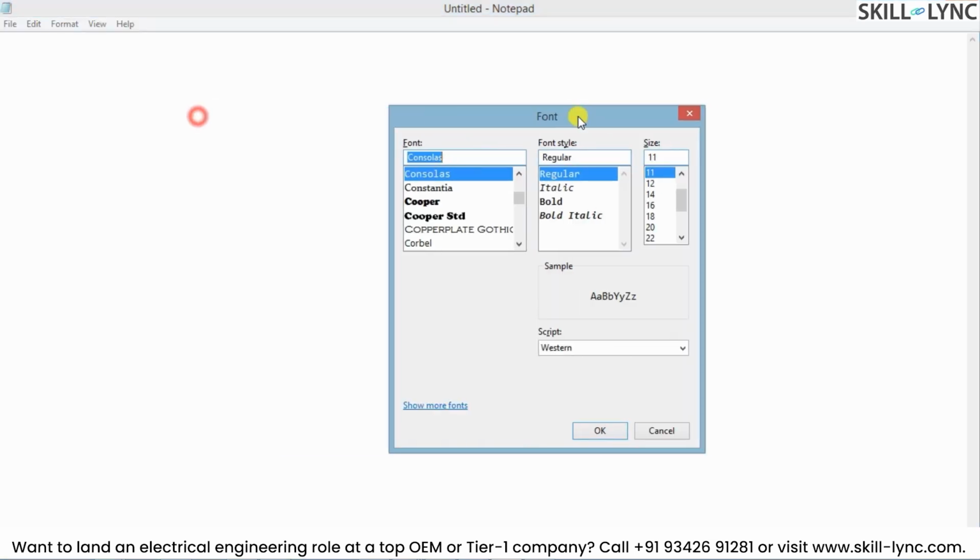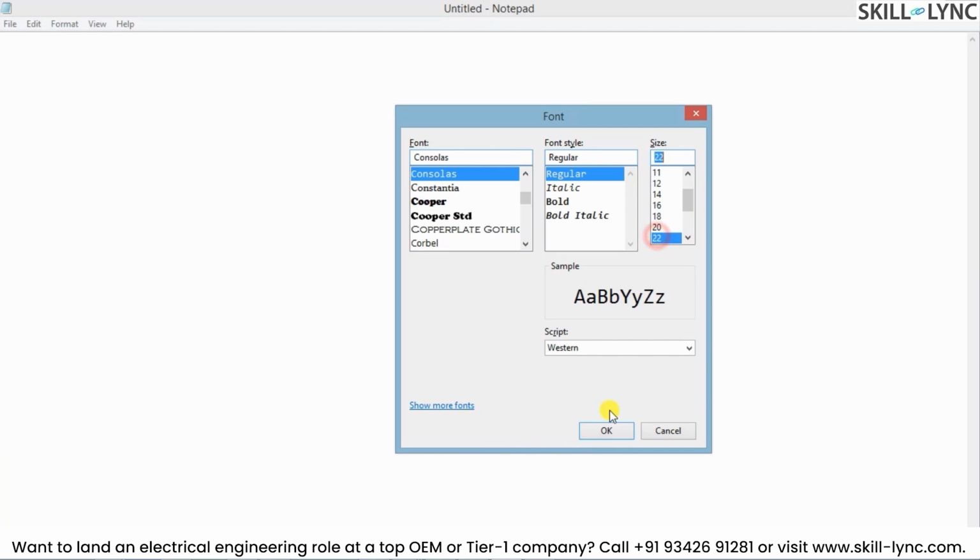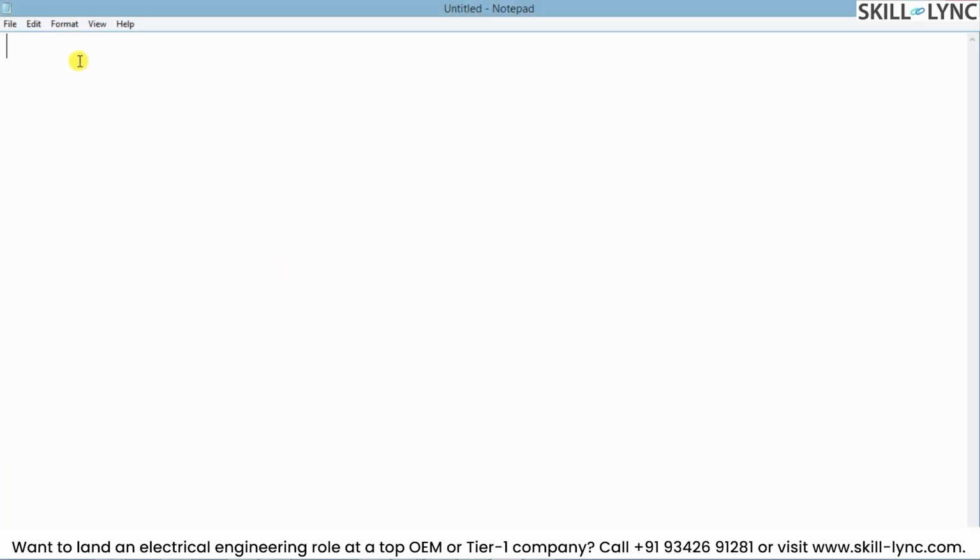Let me just increase the font size so that it will be easy for us to read. To start off, always the Lisp routines should start with an open and close parenthesis. Right now we'll try to emulate a zoom function as well as a circle draw function and assign that a function name, test.